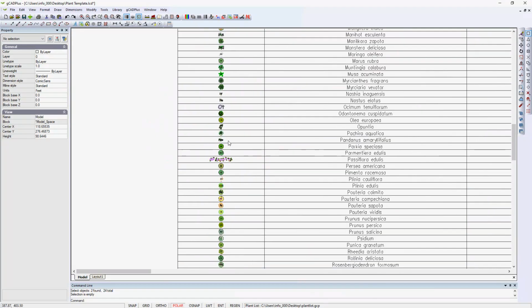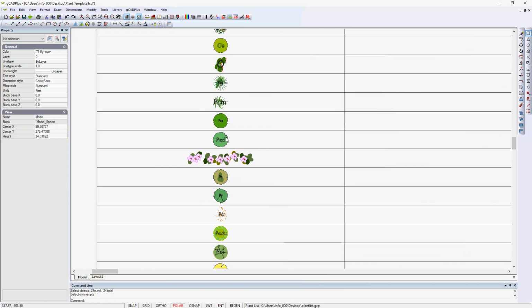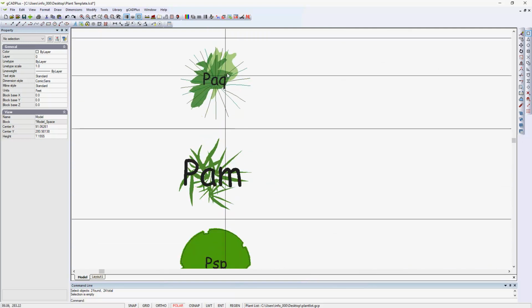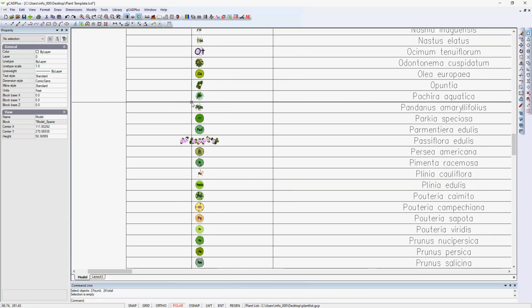If we zoom in on that particular symbol, PA, it must be, here it is up here, PAQ is the text, but the block itself is called PA. So now it's behaving normally, doesn't flood out, so now everything works nicely, and the symbol doesn't overwrite entries in the next row above and below. So do take care when using polyline width. By setting a numeric width, you can cause some grief in using symbols in the schedule.